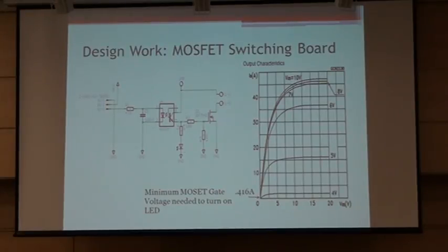As I said in the previous slide, the opto-isolator provides the correct voltage to turn on the MOSFET transistor, which is acting as our switch to the load. Again, this is the same schematic I showed in an earlier slide. So the microcontroller sends a 3.3 volt signal through the opto-isolator, which draws a 12 volt signal through the transistor and into the gate of the MOSFET.